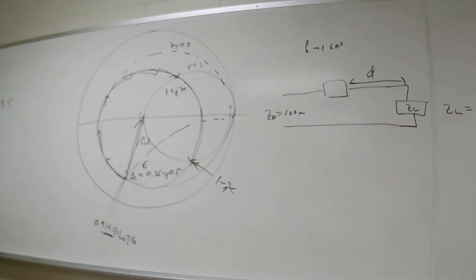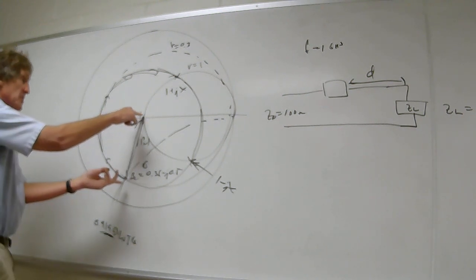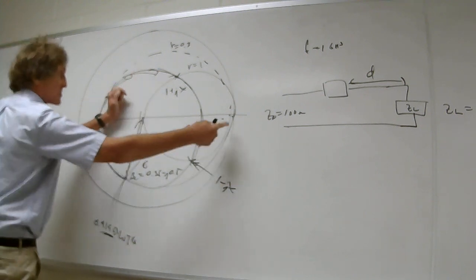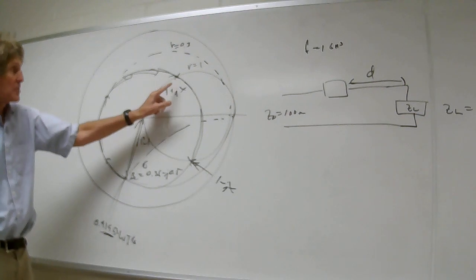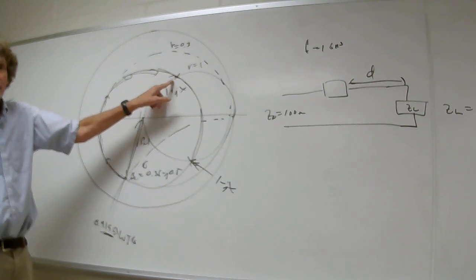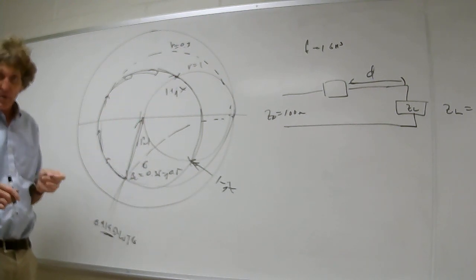It's not necessarily just this problem, but whatever that jX is, we're not going to know what it is. It's whatever is intersecting with the one circle. The circle you're drawing intersects the one circle here. So if you hit the one circle, the magnitude of the real part is 1, and the imaginary part is to be determined. You all with me on this, class?